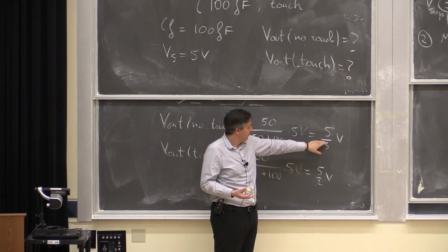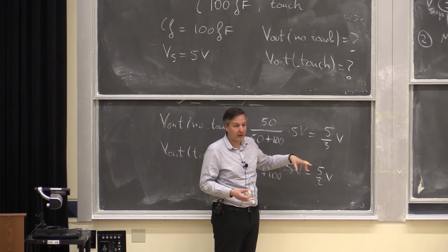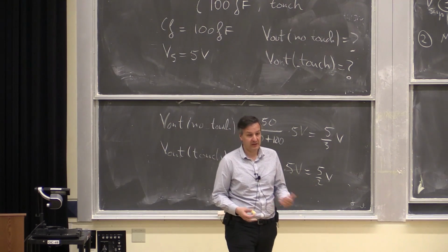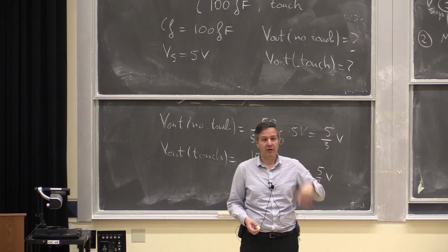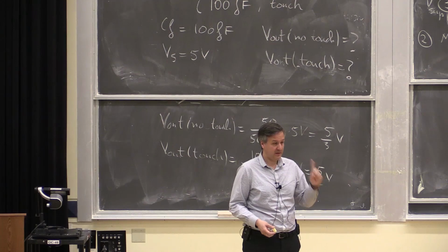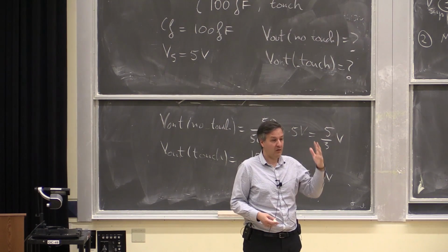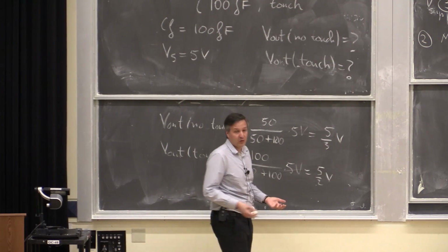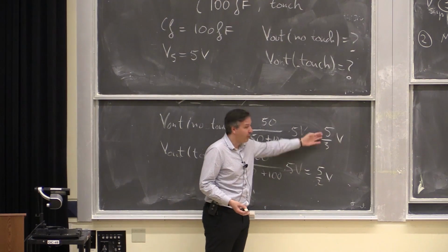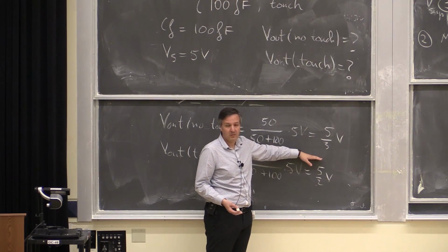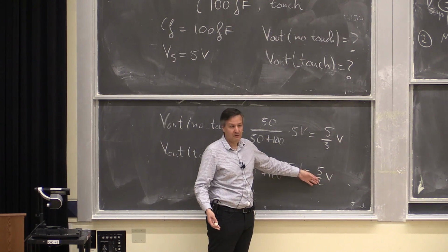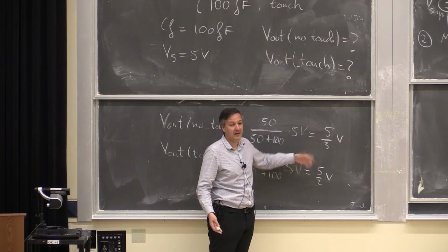And we'll do that circuit very shortly, and you'll use it in the lab a lot. Computers basically like a lot these types of circuit that will just tell them, hey, there's something there or not. That's a single bit of information, 1 or a 0. And these kinds of circuits are called comparators. I just want to compare these two values to some other reference value and know, okay, if it's below that, I get a no touch. If it's above that, I get a touch condition.